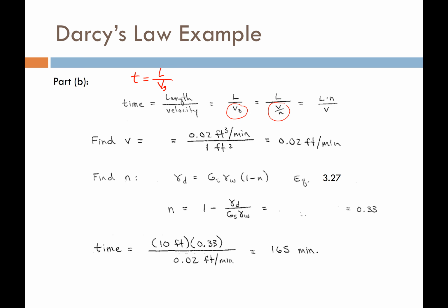We can compute discharge velocity from Darcy's equation, because remember that V is equal to K times I from Darcy's law. And then we have, of course, divided by the porosity to get us to the seepage velocity. So I can do some math quickly, and this is the relationship I'm going to use for this particular problem. Well, how do we get then the discharge velocity?